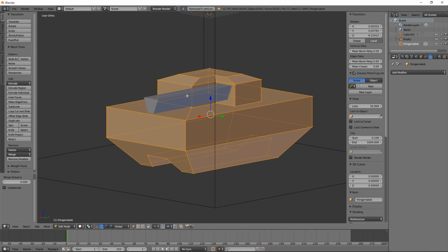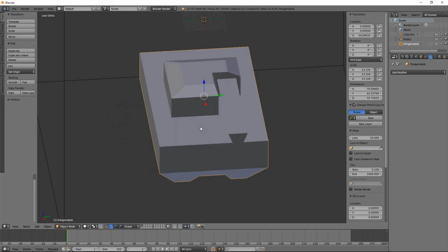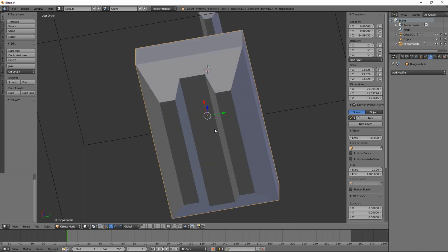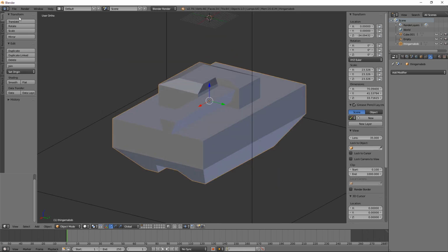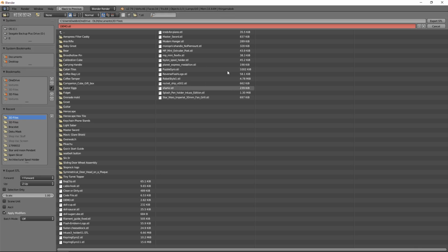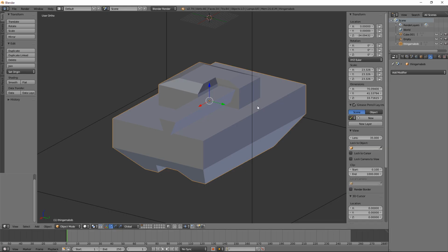It removes 0 vertices. So we want to make sure that there's no vertexes on top of vertexes, that the thing is actually sealed up. There we go. There's another model for you. Let's export this and I'll show you that I didn't even join these two together. They're just two separate blocks, but it'll still work.